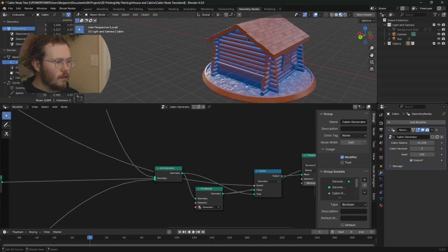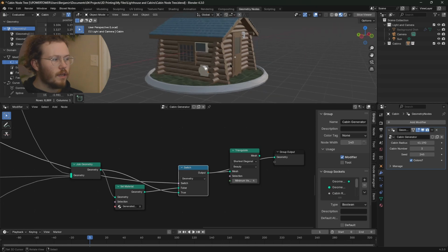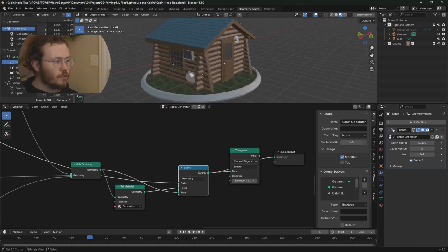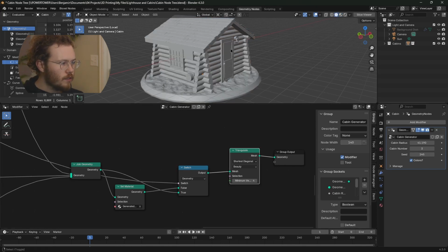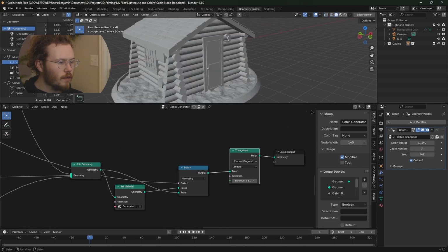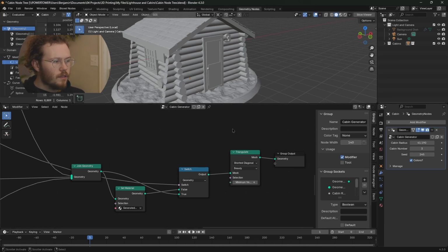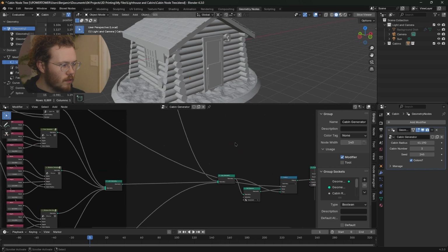And then if you don't want that, got that switch there, so you can have it all broken out into the individual colors for the different parts. And then we've got triangulate, that just goes one quick run through at the very end to make sure that everything is as clean a geometry as we can get. Yeah, as clean as you can get with the methods we've done before. That just helps make the slicer a little bit happier.